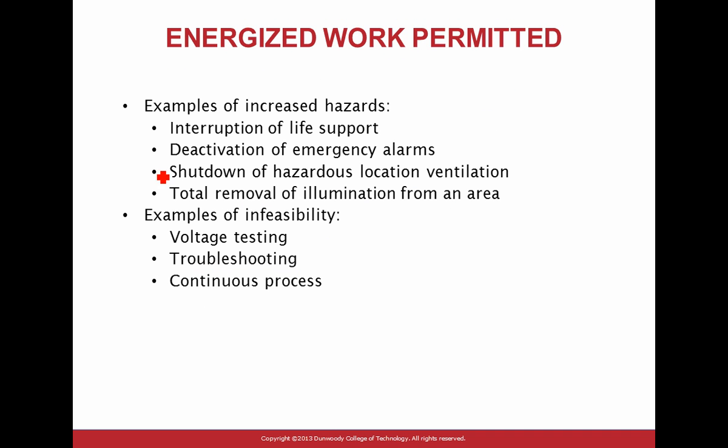Okay, here's an example where you can use the exception. Increased hazards. Look at this. Interruption of life support: anything related to life safety or life support circuits, you can work on energized. Deactivation of emergency alarm system, that also has to do with life support. Shutdown of hazardous location ventilation system.